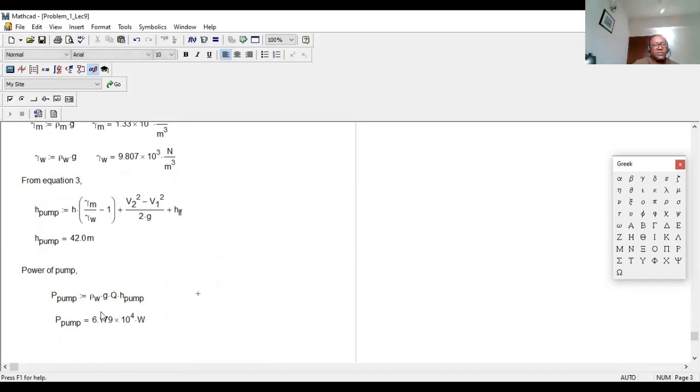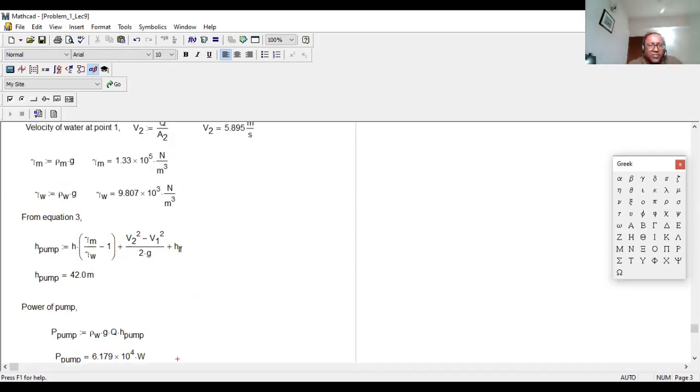I'll get the power of the pump, rho G Q H pump. So just put all the values over here. You get the power of the pump. Then you can convert to kilowatt. Okay. So far, any question? No? Anyone? Any question?